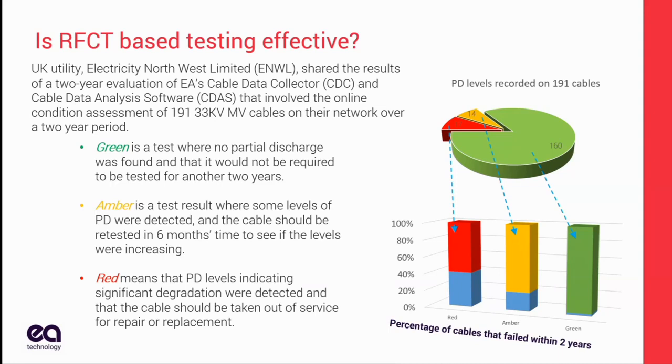What was unique about this is they didn't fix anything. They were evaluating the technology to see if it worked. So they did not fix the red ones or the amber ones. Within 2 years, 40% of the red categorized cables failed. 40% within 2 years. In the amber, 20% failed. And in the green, less than 2%.